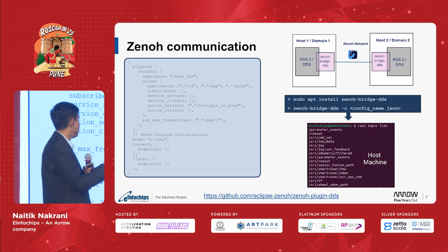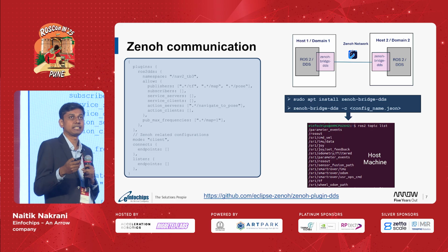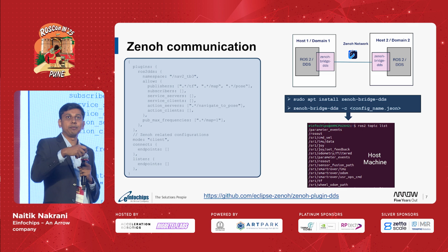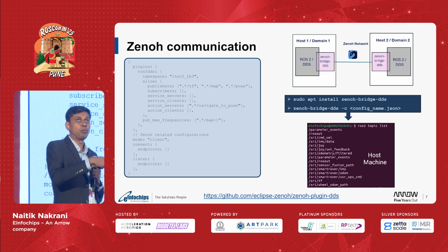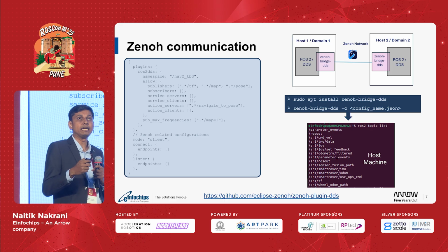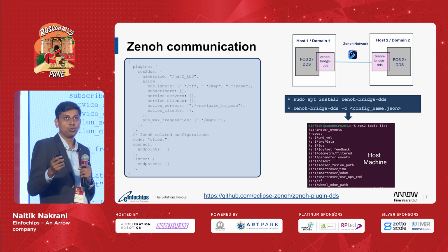There are certain config parameters that you might need to set, which take care of what type of ROS2 topics you need to connect between your robots and OpenRMF. Here you can control different topics that need to be published in between, and also you can take care of their frequencies as well. Mostly what OpenRMF needs is a transform, and how it controls your robot is through your navigation stack action, which is a navigate to goal action.